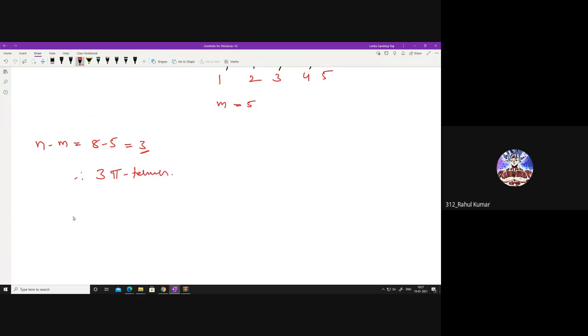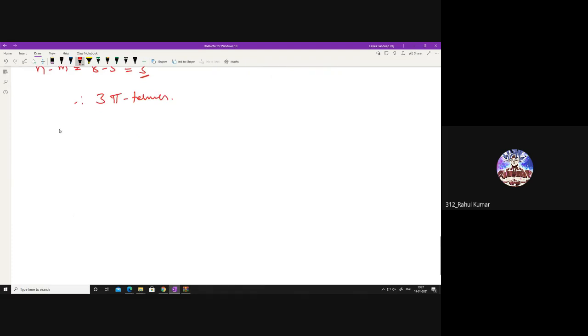So for that, let us take these terms here. The terms here are mu, rho, k, cp, delta t, v, l, and h. These are the 8 things. So for taking this into pi terms, let me define my first pi term. Let me call it pi 1. For this, what I'm doing is, this is equal to mu into k into v into l. See, mu k v l. This I will call the core group.